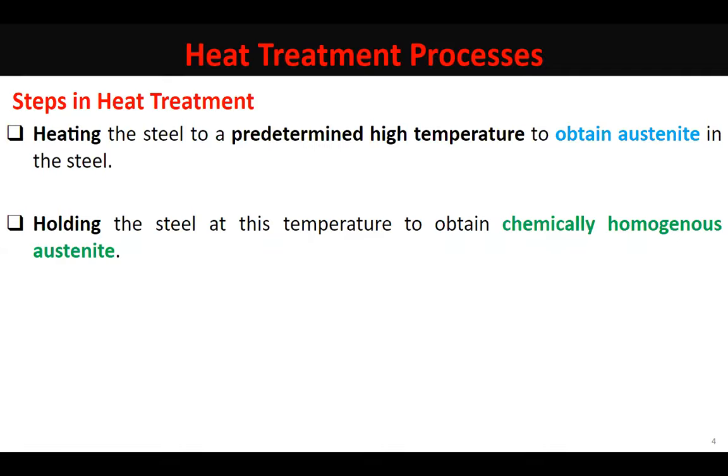When this freshly formed gamma iron dissolves the carbon liberated by cementite into it, carbon in gamma iron, you know, is austenite, and this is how austenite begins to form. But it is an experimentally proven fact now that austenite is getting formed through pearlite dissolution. Pearlite dissolution means that its ferrite and cementite is getting dissolved.